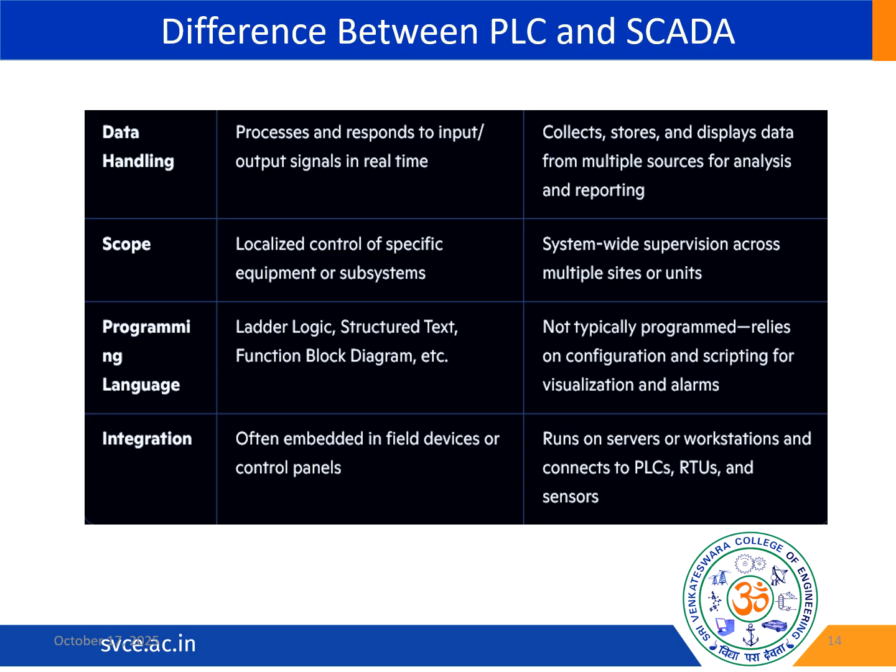So you have learned about the basic differences between SCADA and PLCs, and in some cases people confuse the two. Here you have to understand that PLC is a programmable logic controller. This controller is essentially a rugged mini computer that sits in the field within a panel. The PLC will monitor the state of its inputs, for example the speed of a motor, depending on the program inside.